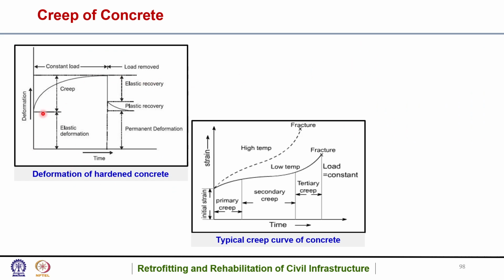So it is a deformation of hardened concrete. If you see, initially there is elastic deformation, that means it is recoverable. Initially it is instantaneous elastic deformation. But as time progresses, the creep occurs. Under constant load the creep occurs, due to sustained loading.